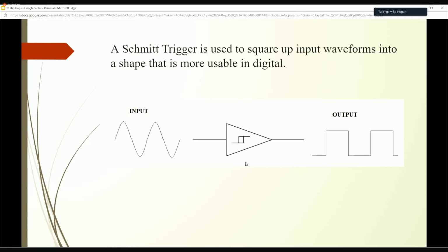Basically this Schmitt trigger is going to trigger at a certain voltage, and it's going to cut it off, right? And so we get this off, on, off, on, back and forth, a really sharp square wave that works well for us when we're dealing with these flip-flops. We're avoiding this sine wave input, working toward this square wave.